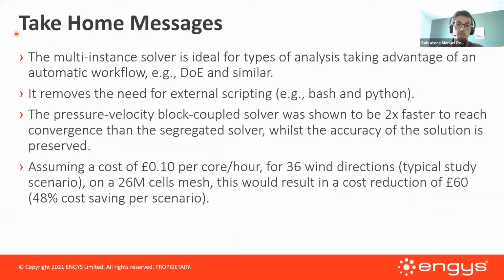Some take-home messages. We have shown the capability of our multi-instance framework in conjunction with the coupled solver algorithm. The multi-instance framework is ideal for types of analysis which take advantage of automatic workflow, such as a design of experiment analysis or similar. So it can also apply to other types of analysis. The pedestrian comfort is just specifications, and it removes the need for external scripting. The pressure-velocity block coupled solver was shown to be, for this specific application and these mesh sizes, 2 times faster to reach the convergence than the segregated one, whilst the accuracy of the solution is preserved.